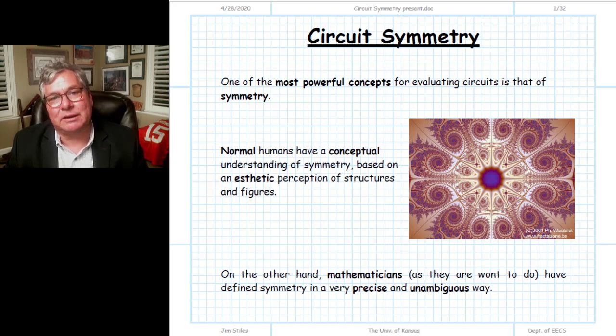If we have a device with a certain scattering matrix that we desire, we can look at the scattering matrix itself, and from that discern a lot about what the resulting circuit that would realize it must exhibit: the symmetries, the topology of that circuit.